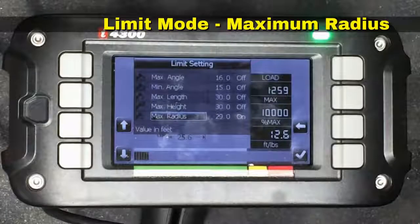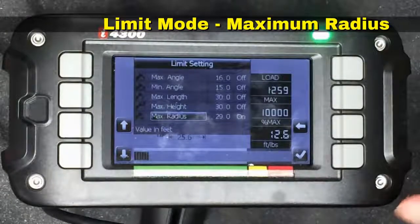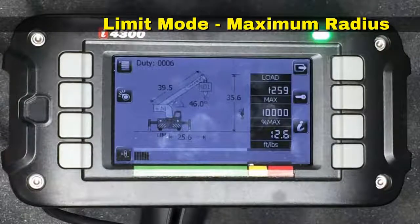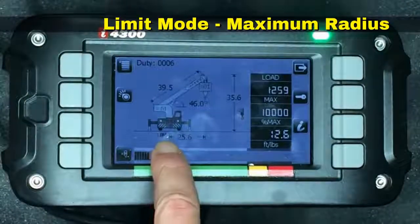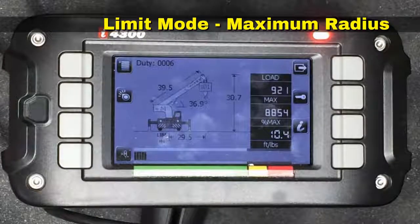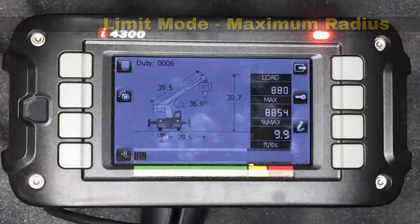I've turned on the maximum radius, and it's currently set for 29 feet. We'll go back to the main screen, and we see that we have a limit indication down here next to the radius, indicating that a limit has been turned on. And I'm going to go ahead and increase the radius by altering the boom angle. The radius has now been exceeded, and again we have the arrow pointing towards the right against a flat bar, indicating that we have exceeded the maximum radius that we have set.